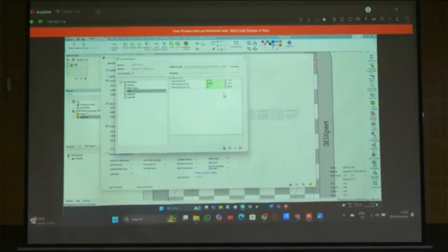So if I reduce the scan speed, what will happen? I mean apart from the defects and all those things. More time to scan, right? The defects you can forget, as we can see defects only after printing, but the printing time we can see in the software itself, right? That is what. It will take more time. But sometimes we need to compromise on the scan speed also, because optimization is there, right? We need to go for lower speed also to get better relative dense components. Okay.